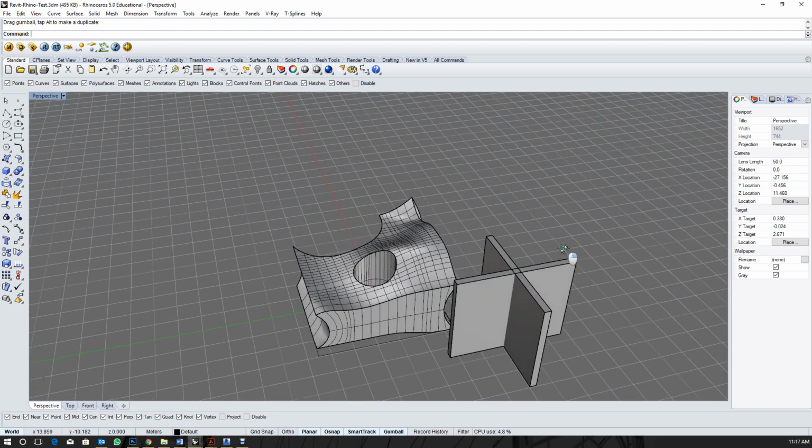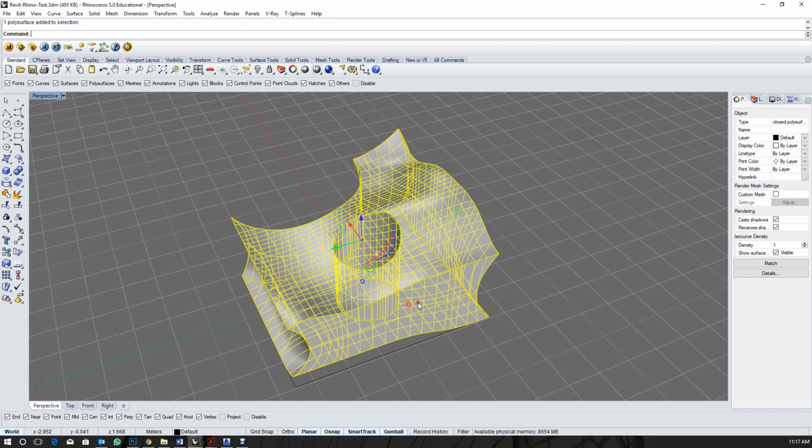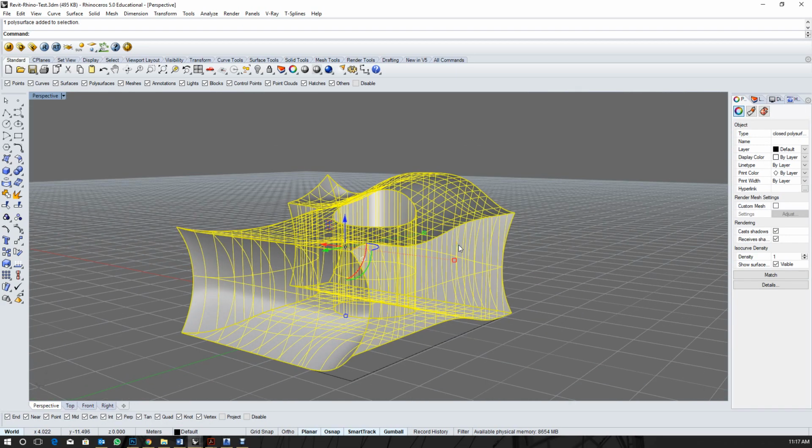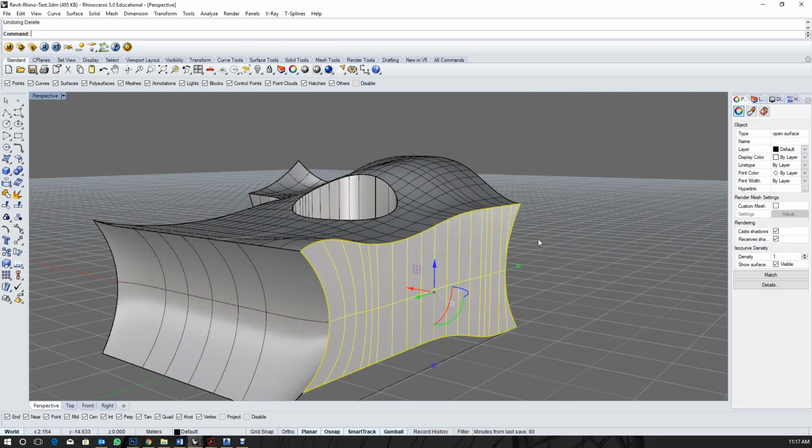Like you're not having something like this where that's one wall and that's another wall with thickness, and you're trying to export that. You want to build everything in surfaces so that you can attach walls onto them in Revit. And this is a geometry just built with surfaces, it has no thickness. So if I exploded that, you would see that it has just single surfaces. That's what you want to export to Revit.